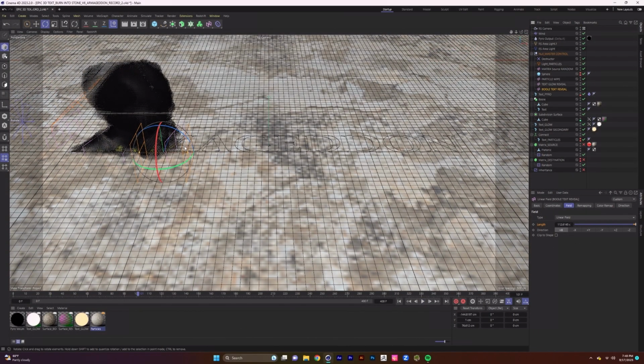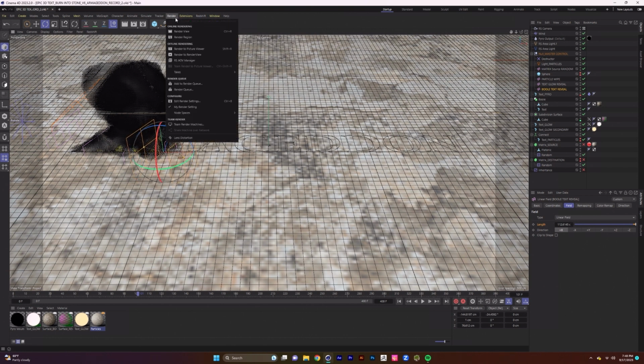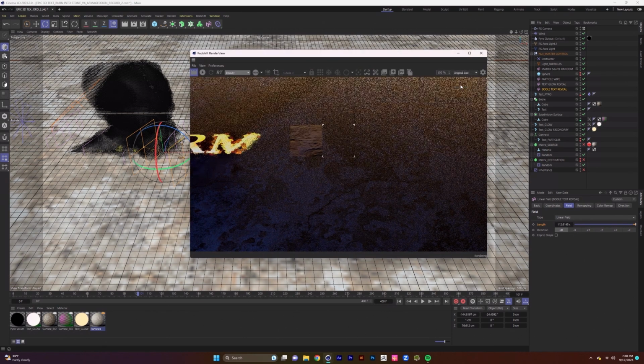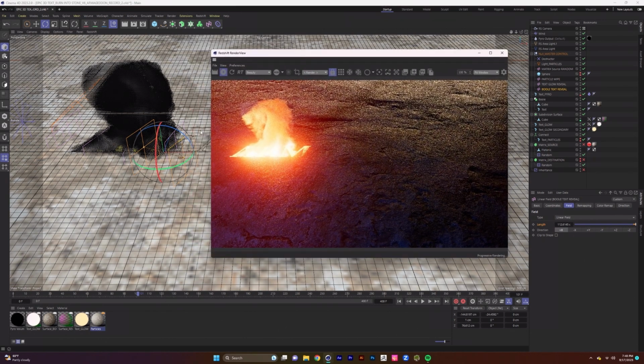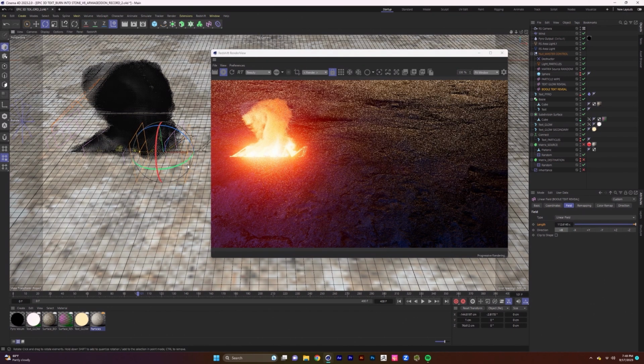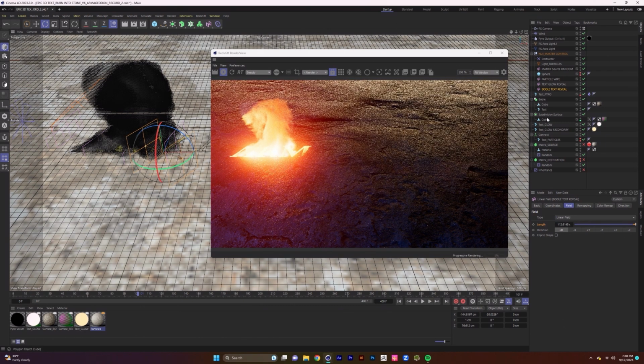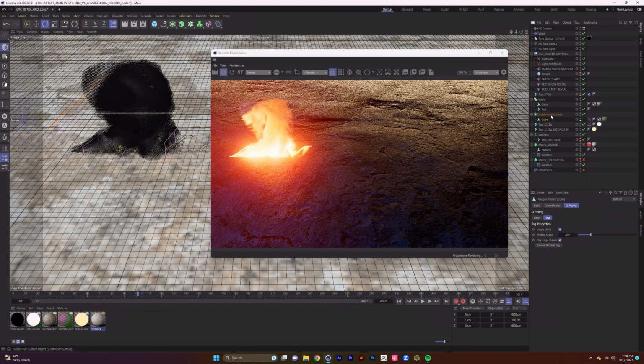What I like to do is also angle my fields a little bit so the Boole text is revealed at more of an angle and not just flat on vertical. And if you want more detail in the text reveal, you see it being wiped on and it looks kind of like a blocky, chunky movement. You can always increase the subdivision like so, and that will help get rid of the blockiness.